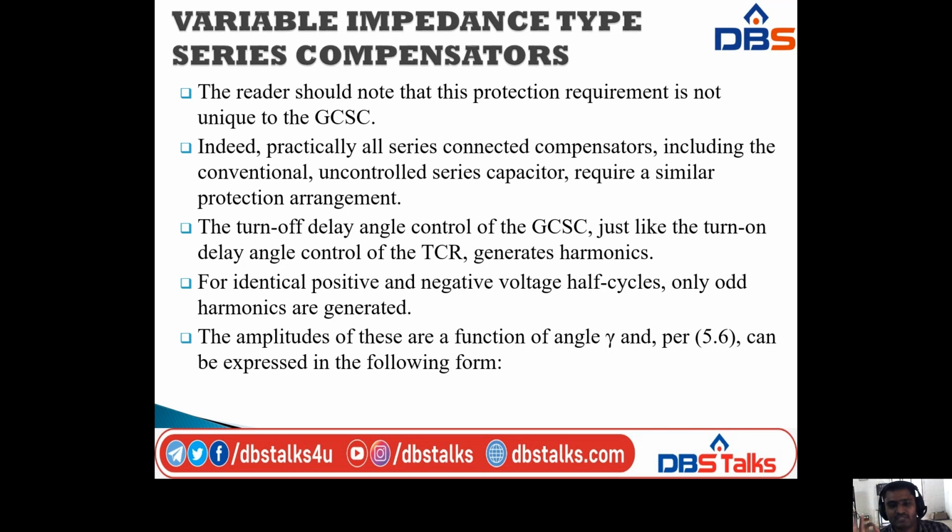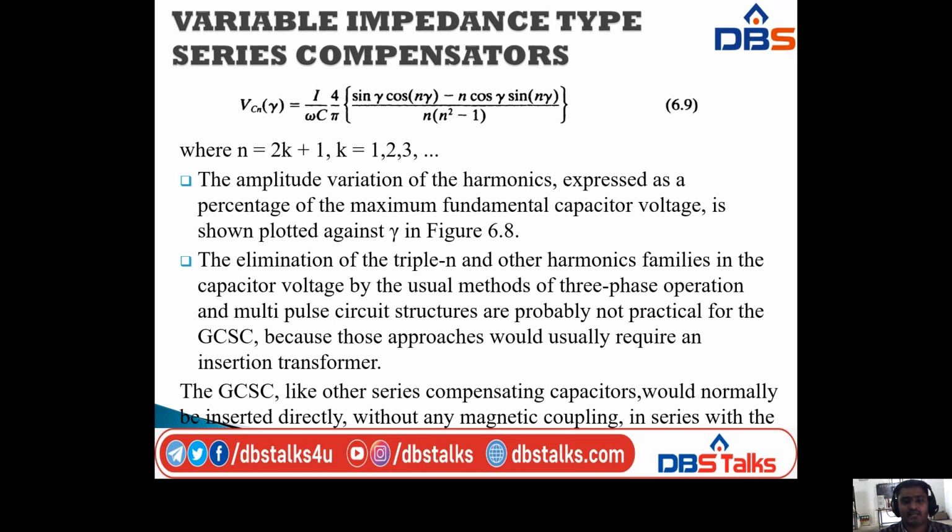The amplitudes of these are a function of angle gamma, and from equation 5.6 can be expressed in the following form: VCN of gamma is equal to 1 by omega C into 4 by pi into (sin gamma cos of n gamma minus n cos gamma sin of n gamma) by n into (n square minus 1), where n is equal to 2k plus 1, and k is equal to 1, 2, 3 and so on.